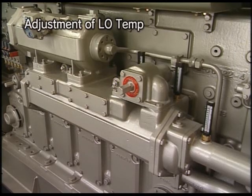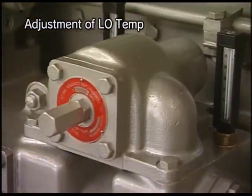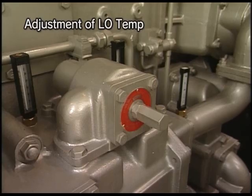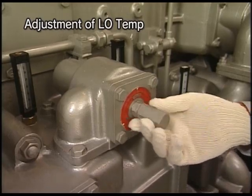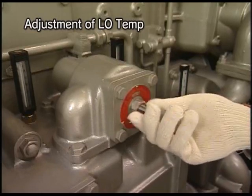I will continue to explain the procedure for operating lube oil temperature adjustment valve. Remove the cap nut, measure the position of the adjusting bolt, and check the valve.